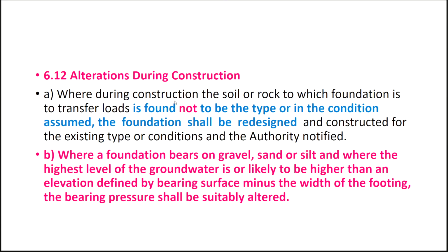Alteration we have already seen. Please, where during the construction. Now what happens is that suppose the design is coming to you based on the soil exploration activities, and you have designed the structure. Now what it says: when during construction the soil or the rock to which the foundation is to transfer load is found not to be the type or in the condition assumed, then the foundation shall be redesigned.